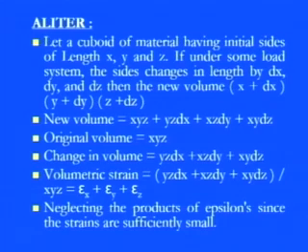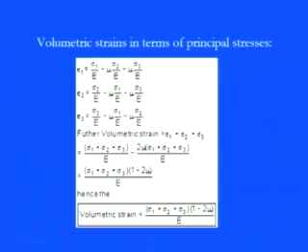The meaning is very simple: even if we are talking about principal planes or principal strains, then we have epsilon 1, epsilon 2, epsilon 3, or if you are talking about the normal strains on the normal planes, we have epsilon x, epsilon y and epsilon z, which will give you the volumetric strain, because again we are neglecting the higher terms of the strains here.